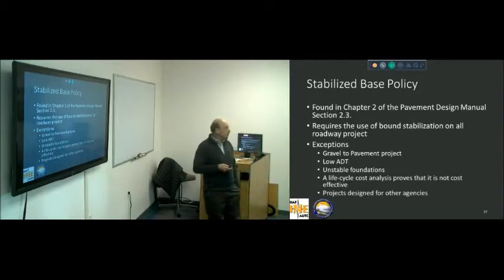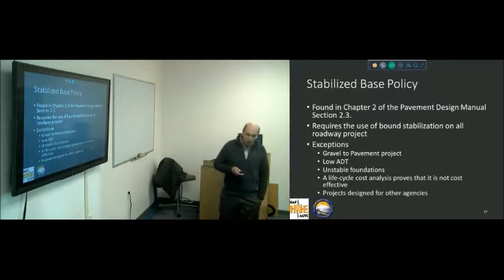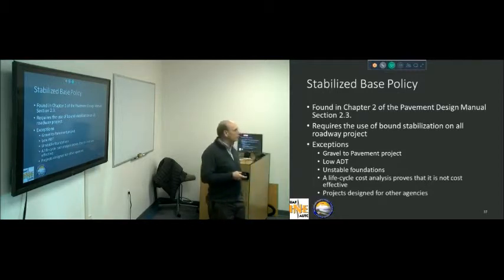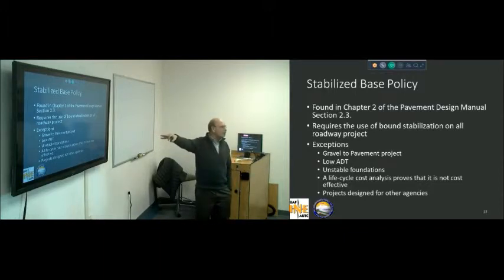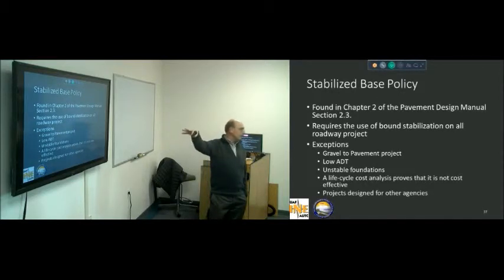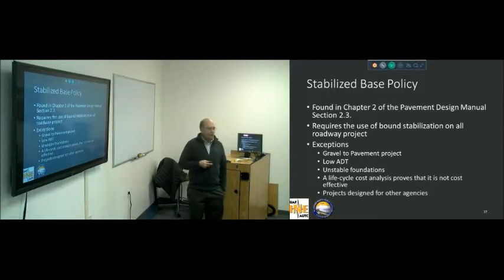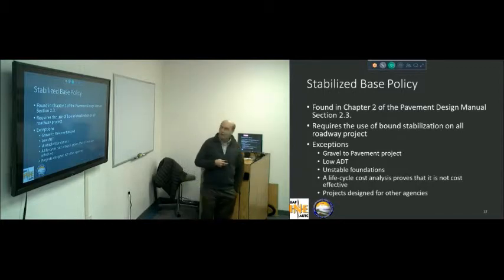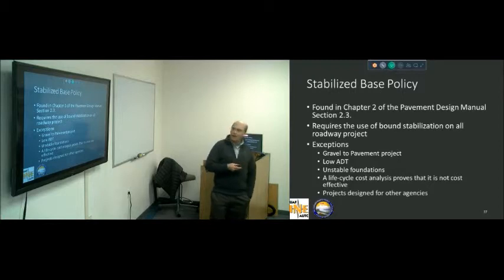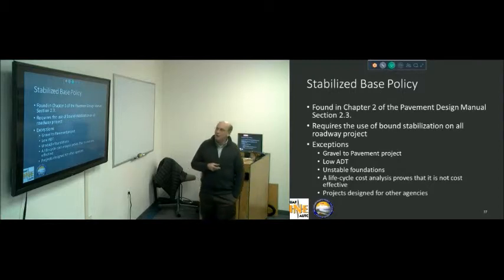If you have an unstable foundation, it's not required, but oddly enough, one of the things we're finding is that on unstable foundations, a stabilized base will actually help lengthen the time that pavement is going to last before it has to be rehabilitated. We did that on a number of projects on the Elliott, and it surprised all of us. We were getting a much longer life before we had to rehabilitate it, and before it settled out and had to be leveled and patched.